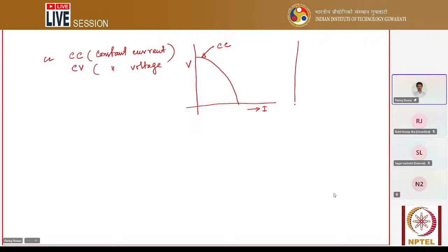Whereas in the case of the constant voltage characteristic curve, always keep in mind that the vertical line is voltage and the horizontal line is current. Here the voltage variation is generally a straight line in nature, flat. So there is only a marginal variation. Now there is another characteristic curve, called the arc characteristic curve, which looks like this. That is very well known to you.